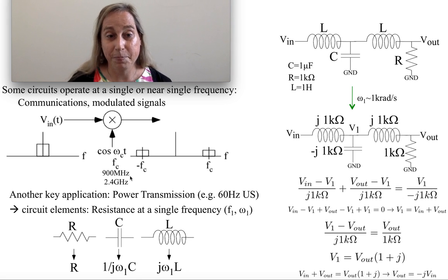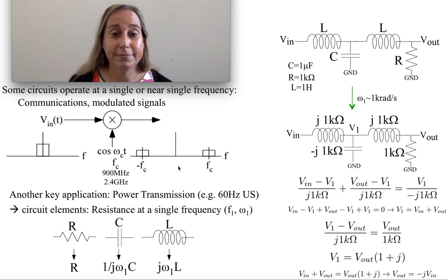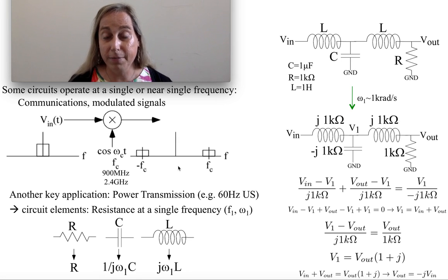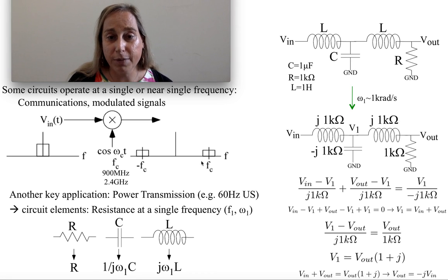Which means I take a signal that has a frequency spectrum like this, and then basically it gets modulated, which means that this action of modulation pushes the frequency responses into these two spaces. So it is a modulation of a signal, which pushes you into higher frequencies, and you get half the height in both cases. You can then, by doing another modulation, push it back down, or at least some part of it back down to baseband.